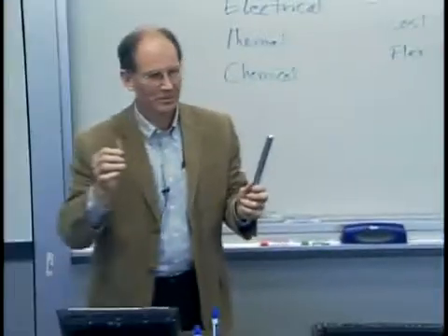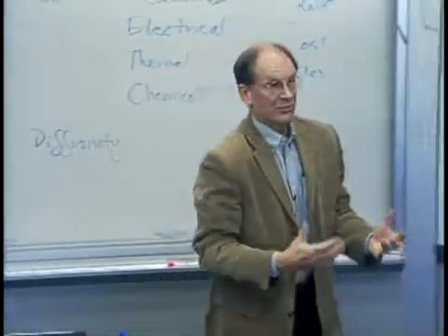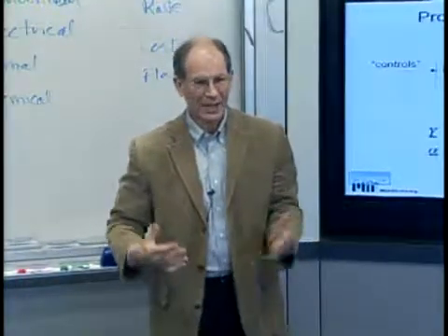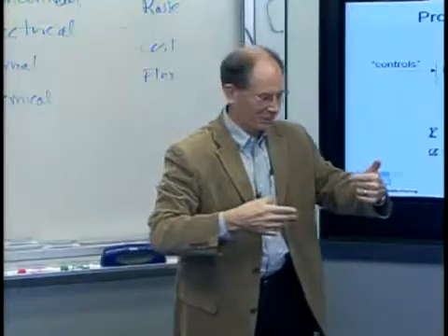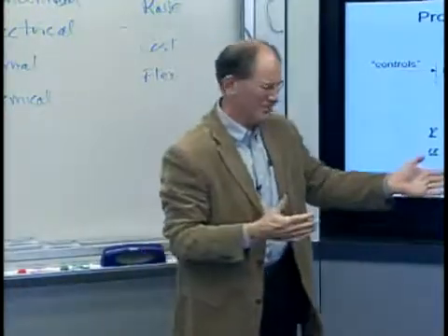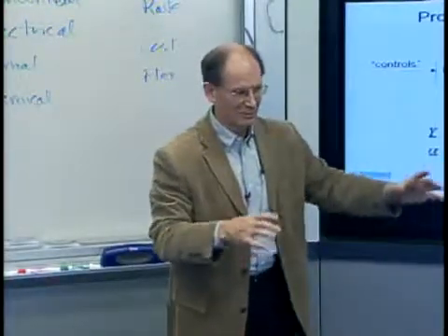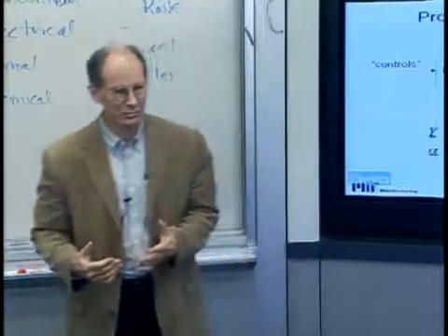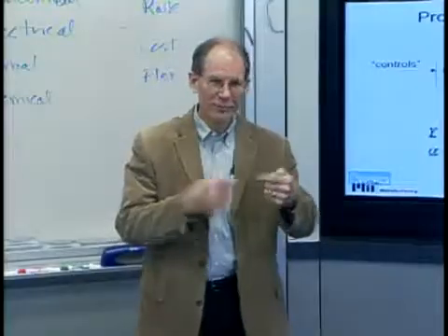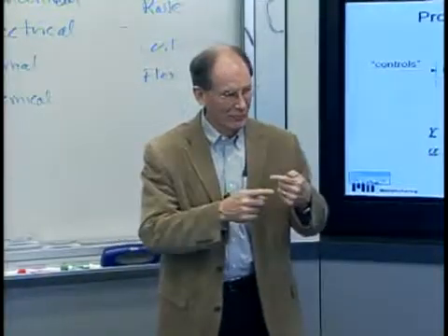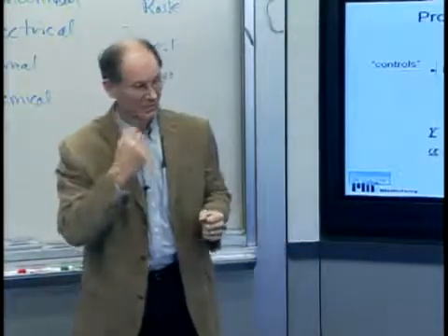So as a minimum, you've got these two sets of variables. You've got how stiff the machine is. How does it react to things like forces? How straight is the machine? If I move this way relative to the axis of rotation, that's your accuracy thing. Those are properties that are not independent of whether it's moving or not, but you look at it and say it's the basic characteristic of the machine. And then you've got these transient ones that are only related to the energy exchange. So you'd agree that if there's no force, there's no energy exchange. But as soon as I have a force and a velocity, I'm putting mechanical power into that thing, and something's going to happen.